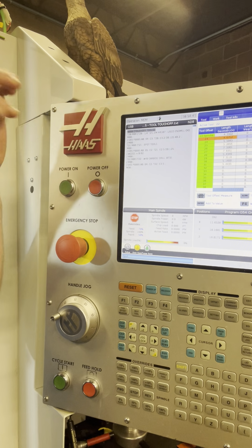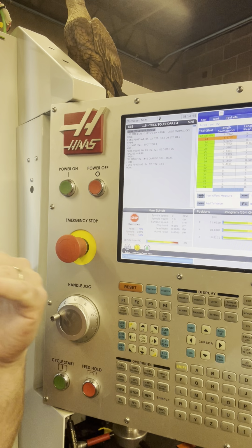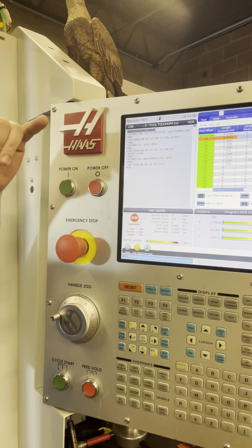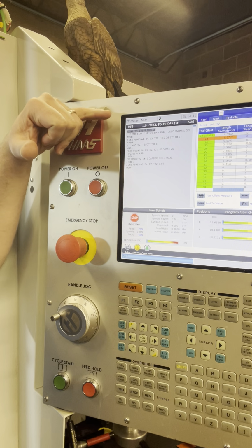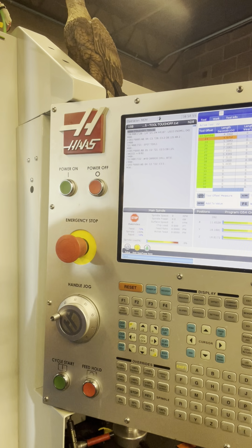I didn't mention this, but this is always at the top of our programs. It's another subsection of the program that we're using at the very beginning. Normally in a program, I'll just do a go-to and jump down over top of this, so when you're running the job, you're not running through the tool touch-offs. Obviously, you don't want to do that. But you can always jump down.